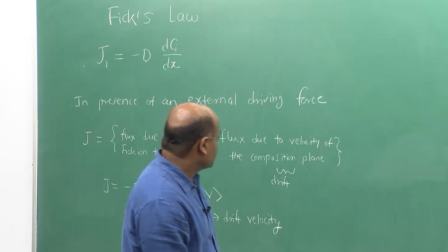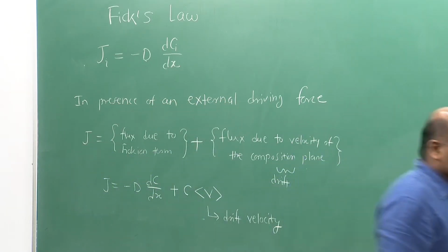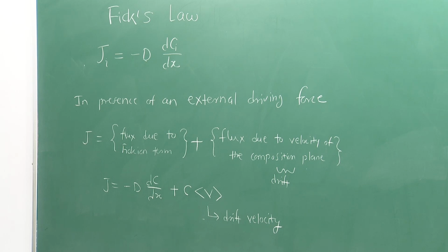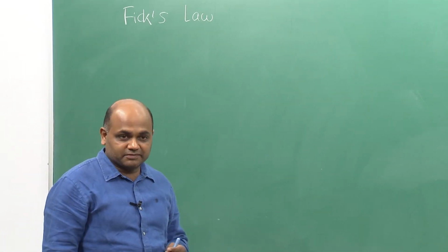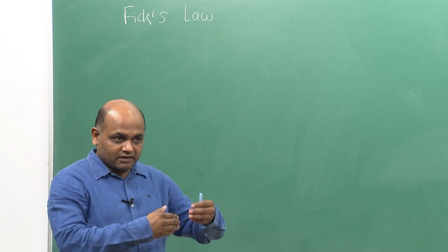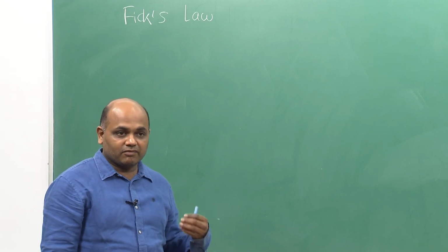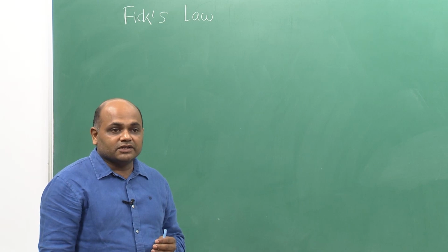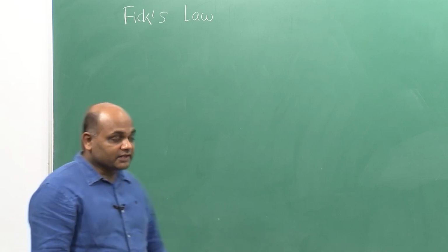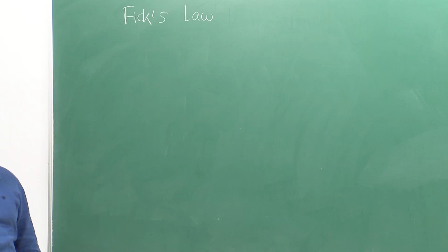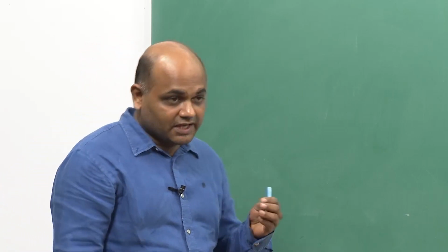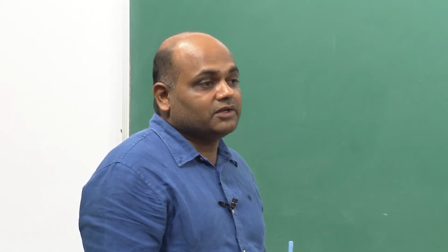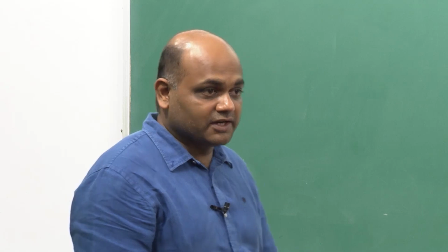Clear? Okay. So, now let us come to the diffusion in solid. Now, we say in solids diffusion occurs by discrete atomic jumps, right. There are interatomic planes and the atom jumps from one plane onto the next plane or within the plane itself, right. So, it is a discrete atomic jump process, whereas here in the phenomenology we assume a continuous concentration gradient, right. So, let us see how these discrete atomic jumps give rise to the net flux down the concentration gradient, right. So, let us try to link the two.